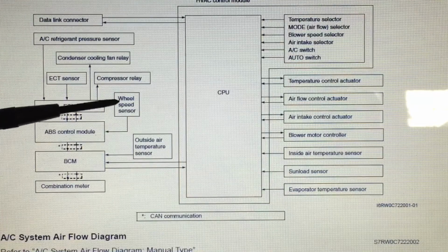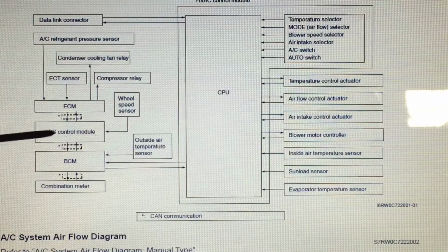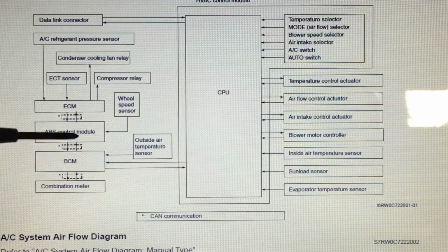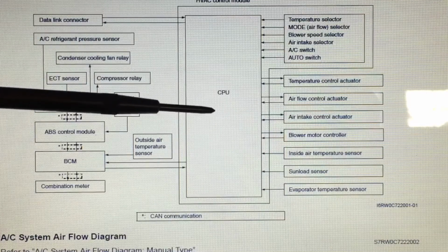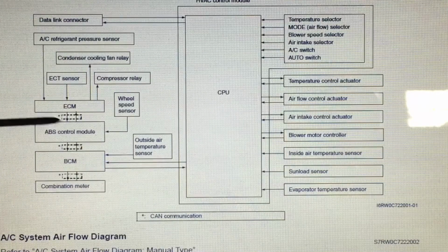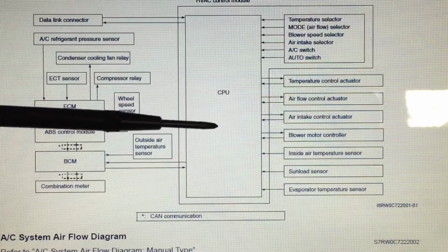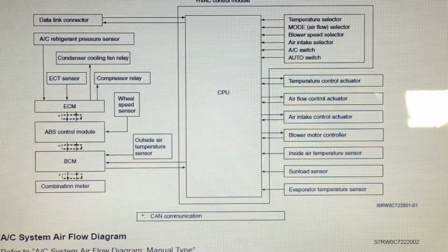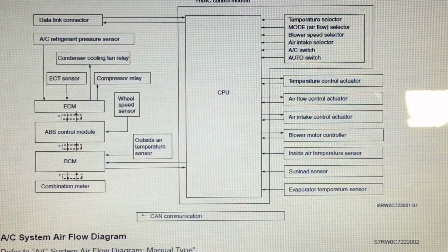The wheel speed is obviously sensed by the ABS control module via the CAN bus. It's exchanged with the various modules in the car, but not the climate control module. It isn't on the CAN bus, but goes through a serial data bus and exchanges data with one of the other modules, and it is wheel speed. So why do you suppose an air conditioning system, climate control system, needs to know the vehicle speed?